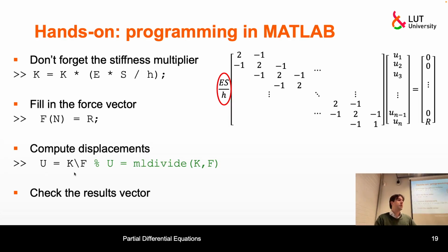And we need just to solve this set of linear algebraic equations. By default, in MATLAB, you can always use this mldivide function, which has a short syntax with this backslash. You can solve this set of equations by inverting your matrix, of course, and multiplying that by the right-hand side. That is absolutely correct.